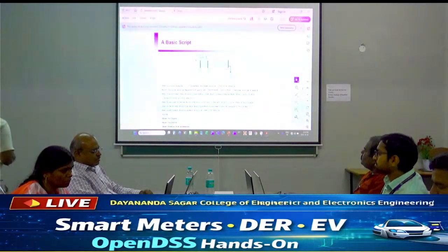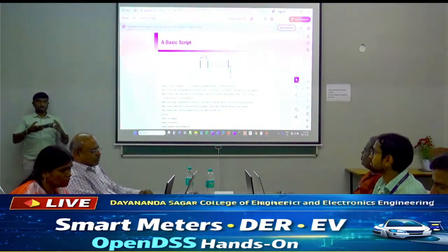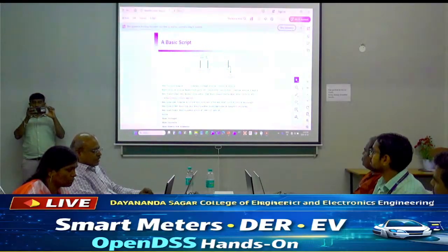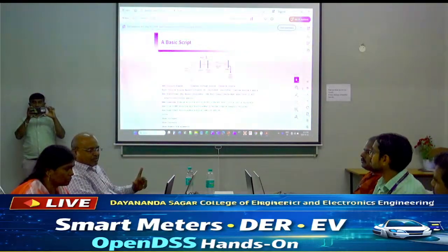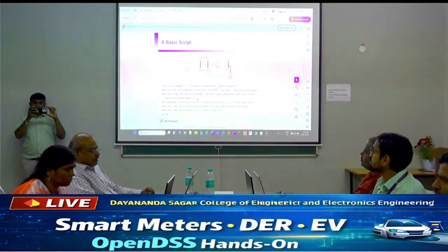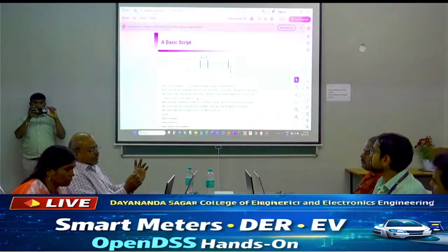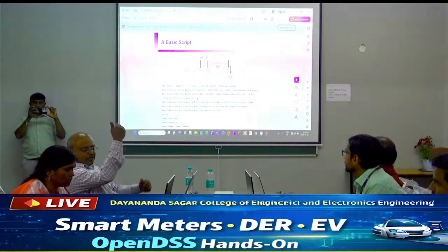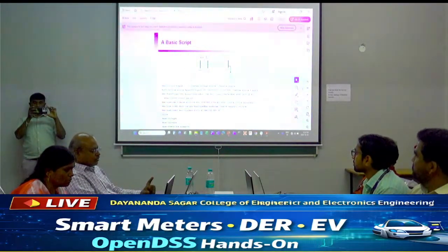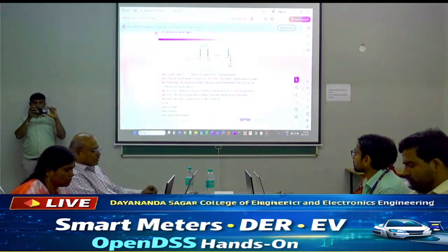So kVs, it is 115 kV this side and 12.47 kV this side, and then the kVA is 20,000 kVA, the same on both sides, and then XHL, I don't remember what it is, reactance. Yeah. So these are some of the parameters. If you go to the user manual, you can find a full list of parameters you can use for defining transformers. So you can model it pretty well actually.